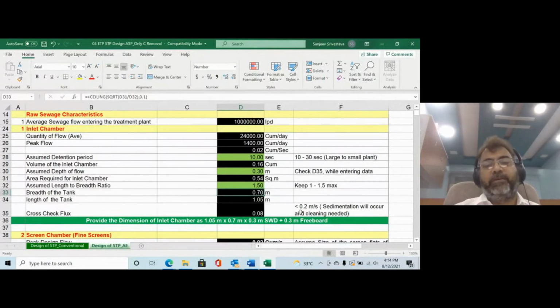I'll say, okay, at such a small 0.7 meter by 1 meter, right, is a very small inlet box. Very small. If you can imagine what is 1 meter, it's just my one arm, right? A very small box. And how much water you are talking about giving it? Almost 24 MLD water, which is coming at a very high flow rate, 1200 meter cube per hour. The water may start jetting out of that box itself. So in such situations, my common sense will prevail.